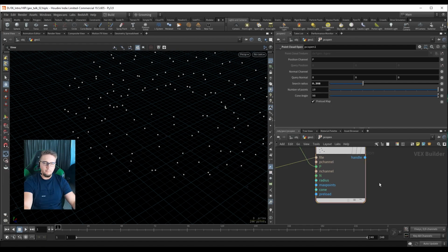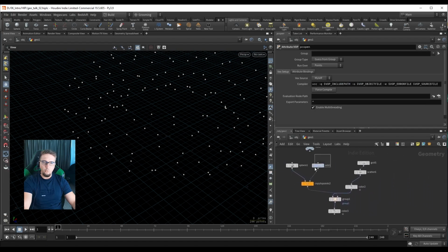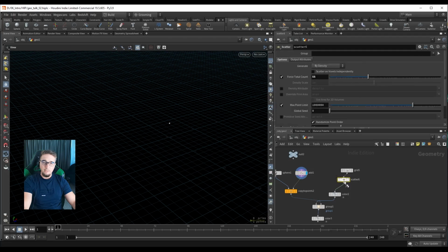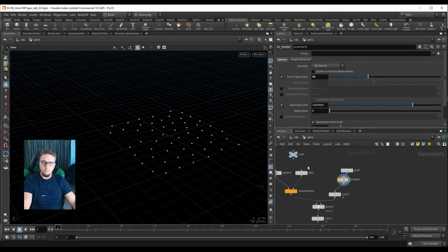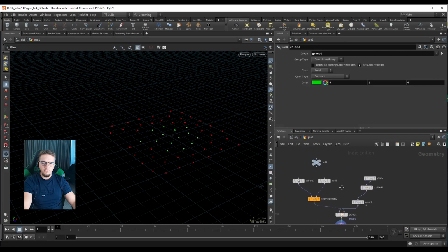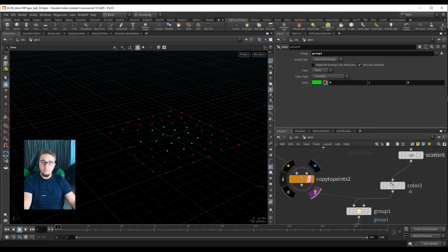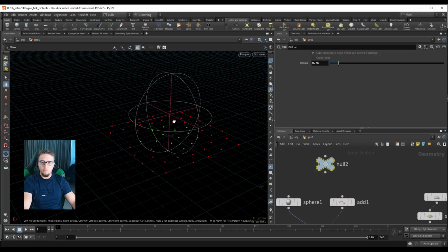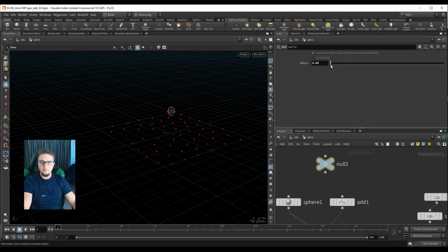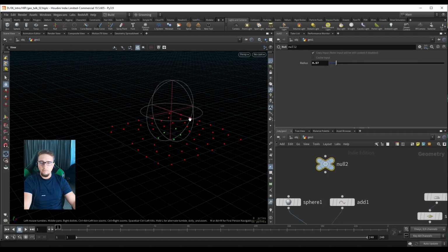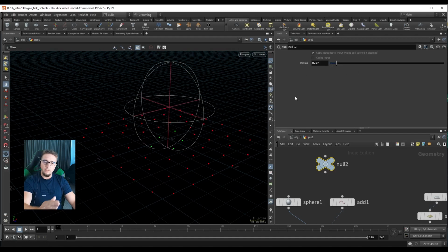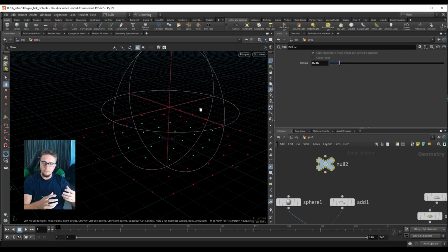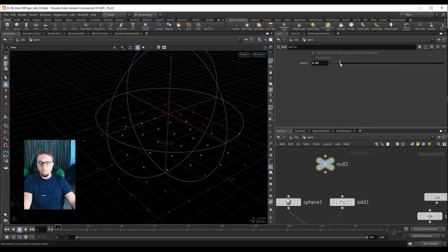So I made a quick setup for this. Let's say we have just a single point here and we want to interact with these points from a scattered geometry. So I'll go to the end result here and preview this invisible sphere that I was talking about, and basically this will be our radius. We can see that as I increase the radius from this point, we start to grab some points from our second geometry, and I can increase this to add more points to this mix. So this is what the radius will do for us in the PCOpen.